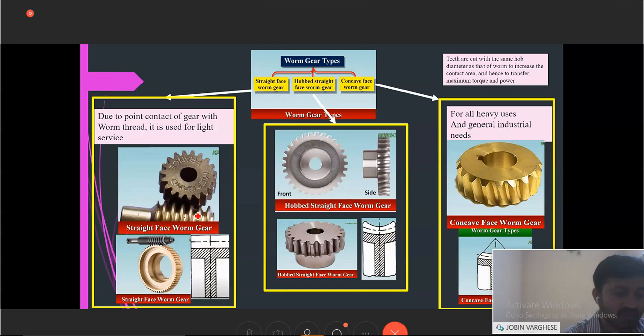The velocity should be well controlled, or else the steel will not be flattened and the rollers will get damaged. However, an electric motor runs at 2000 RPM or so. If the rollers run at 2000 RPM, the rollers will get damaged, the steel will get damaged, and the product will not be obtained.